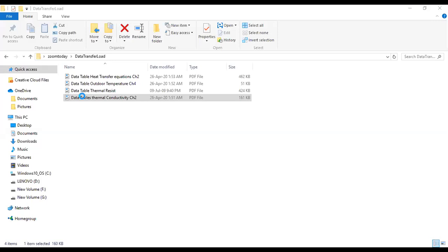This is a typical construction structure of the wall. So these are again outside air space and so on. So example 2.9 here, go through this example, do it by yourself, use this table, and you will become a master of calculating Q is equal to UA delta T, heat transfer. Here you are required to calculate only R total, but here is Q. Q is equal to UA delta T.